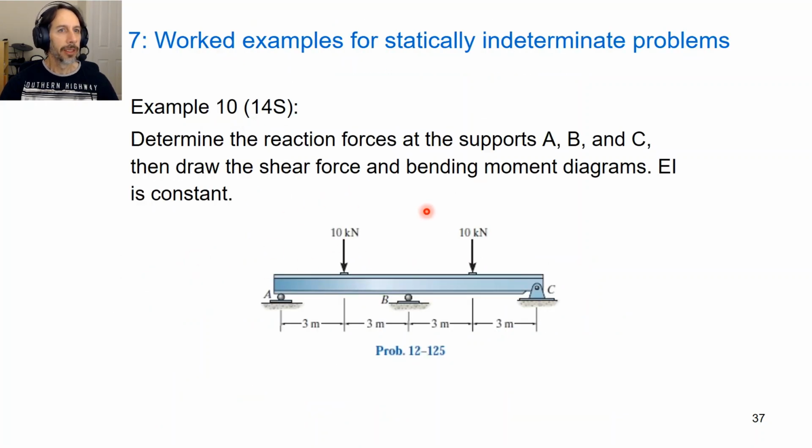Okay, so another example: determine the reaction forces at A, B and C. Again you should be able to identify that this is statically indeterminate because we have a simply supported beam with an extra support in the middle. Take this away and it could still be in equilibrium.